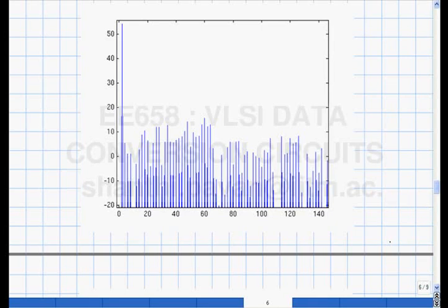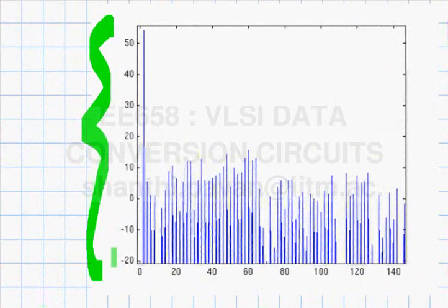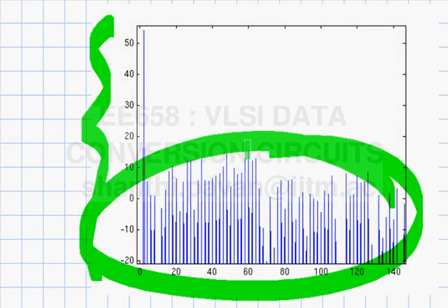Okay, this is a 1024 point FFT. Now, when you had an unquantized sine wave, where were all the bins other than the fundamental? They were all at minus 300 dB, they were all 0. Now you can clearly see that there are a whole bunch of tones which correspond to the Fourier decomposition of